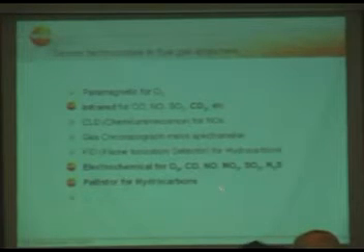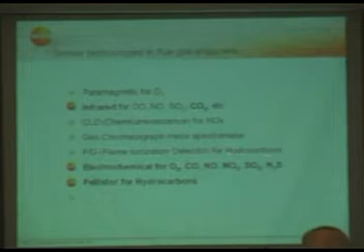Therefore, if you have to measure hydrocarbons in a very low range, you have to use an FID, which is very expensive, but it fits your application and you can fulfill the requirements, having an accurate hydrocarbon reading.